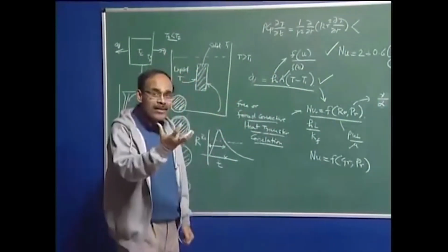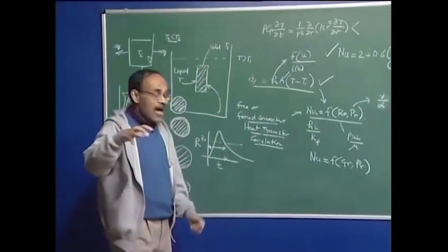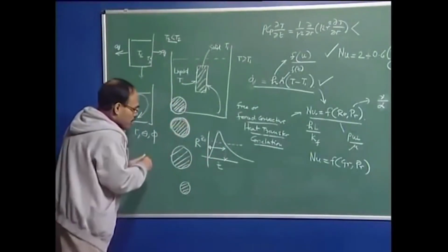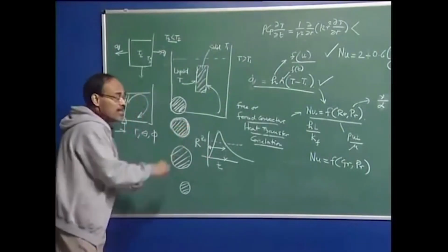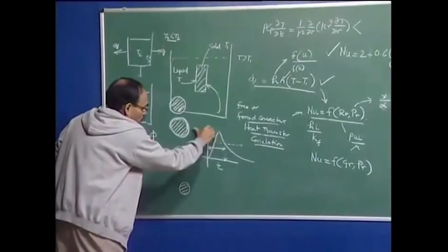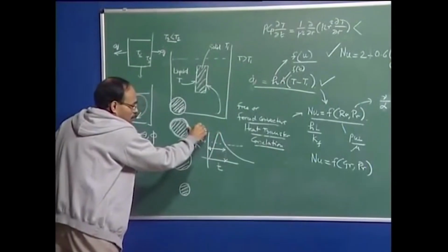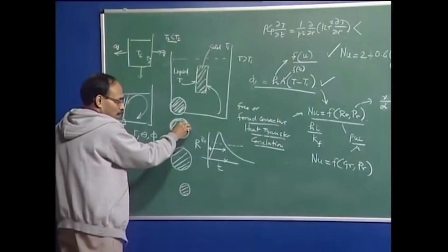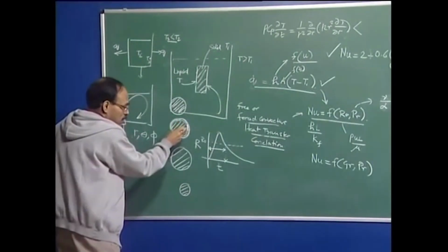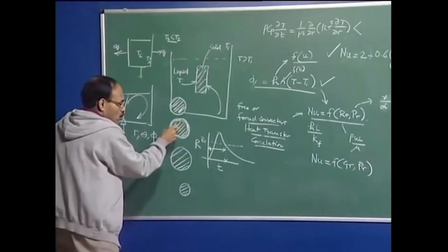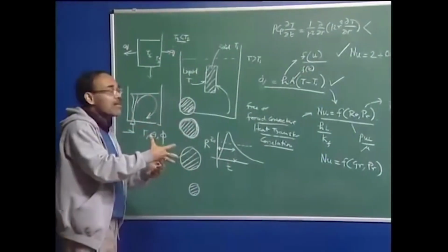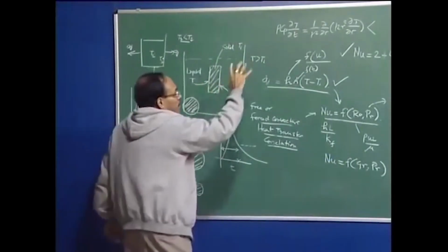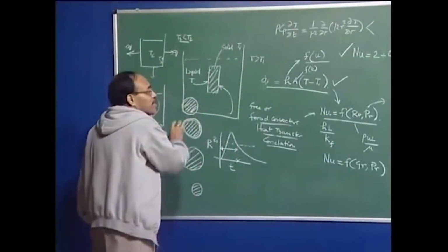So, from somewhere the value of r is to be calculated, and that is from an energy conservation statement at the surface of the solid: the net rate at which heat is flowing into the solid, plus the heat which is evolved or consumed here because of the melting and solidification phenomena, plus the heat which is flowing because of conduction. All three things have to be taken into account in order to predict the temperature profile within the solid or the melting time completely.